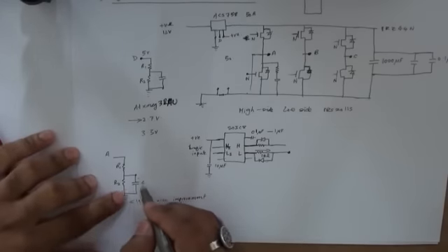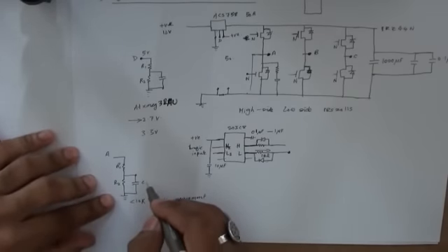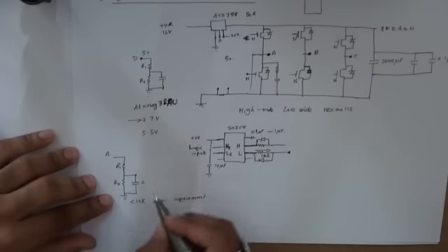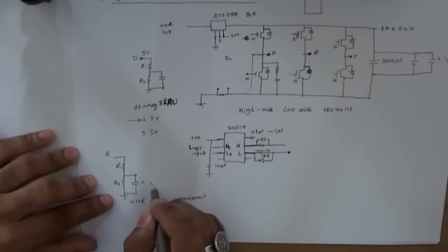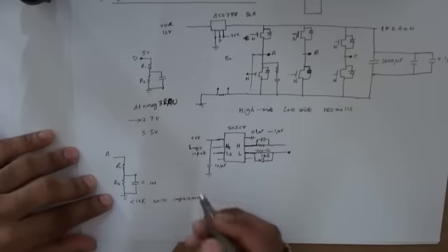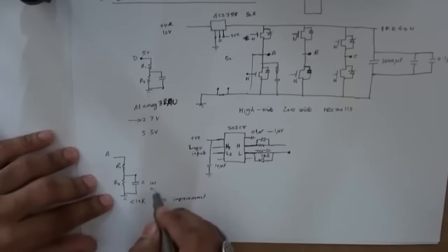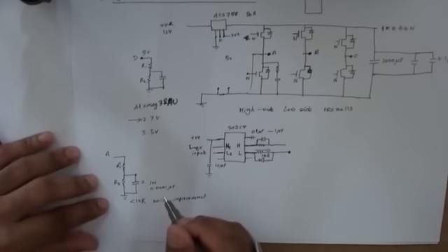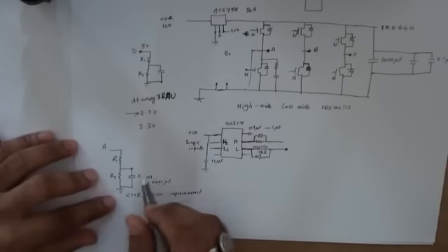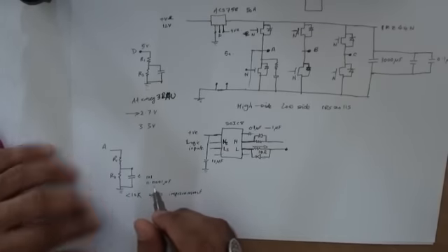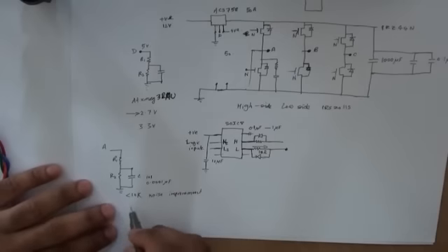For the capacitor, you don't want to have the capacitance too big. You also want to have something like 101. That's what I've used, which is 0.0001 microfarad. The problem is if you have any bigger than that, then the decay would be too quick.